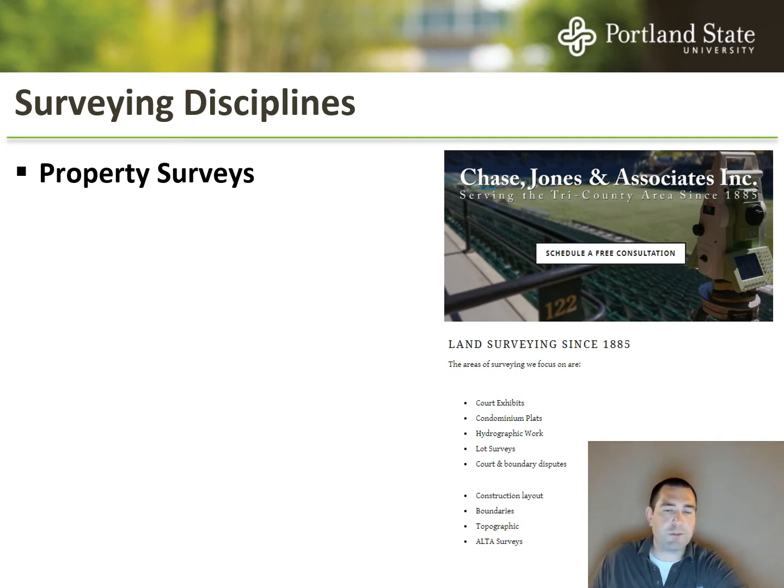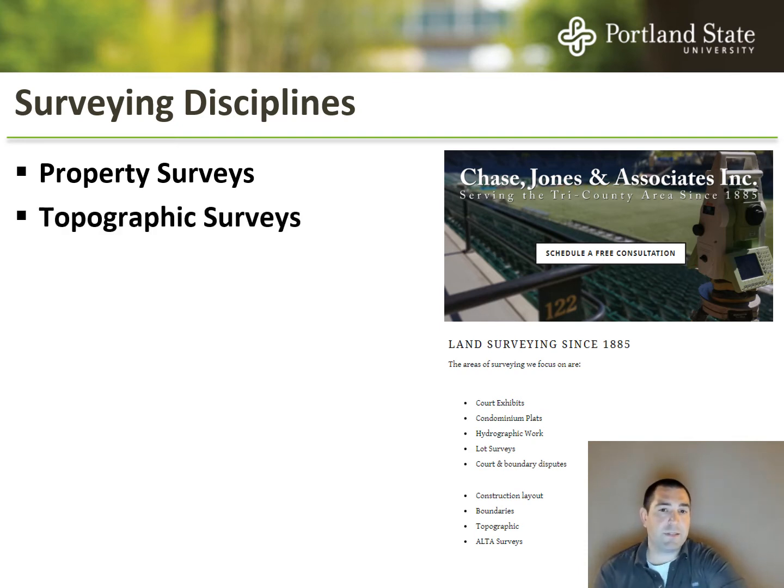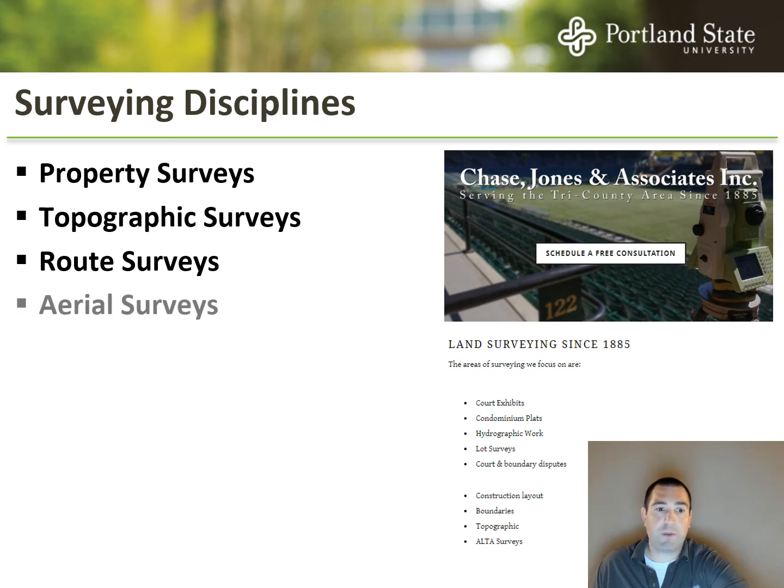Property surveys, getting the legal definition of a property, and then putting down stakes to show where your property boundaries are. That could be one, or going out and platting out new properties as maybe part of a subdivision. Topographic surveys, going out and collecting the existing ground elevation data that's oftentimes used when we first start laying out civil type projects. Route surveys, that's where you have a long and relatively narrow path. It's often done for highways, pipelines, railroads, things like that.